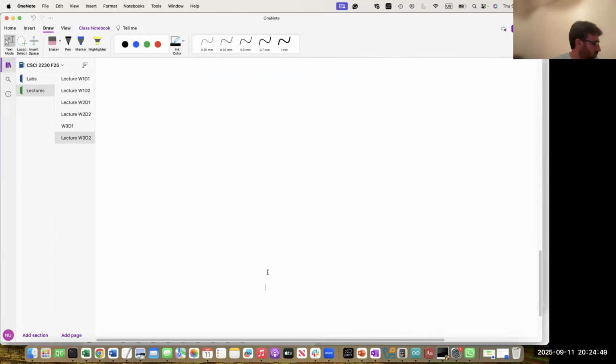Again, I am going to use 4-bit numbers to keep our example simple so that it takes less time. I'm not covering the zero flag because that is simple. If the result of an operation is zero, then our Z flag will be equal to one. If the result of the operation is not zero, then the Z flag will be equal to zero. So I'm not going to cover it in the example.